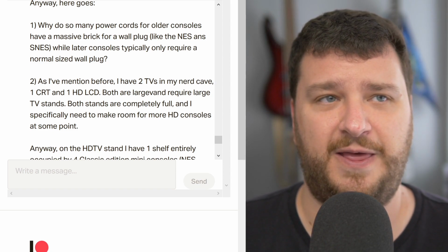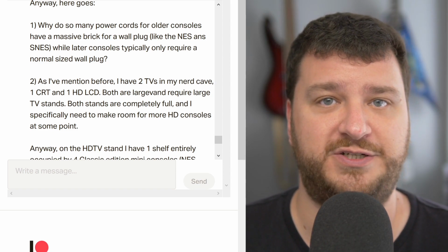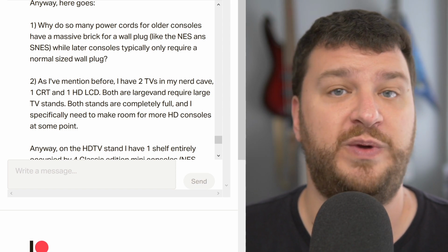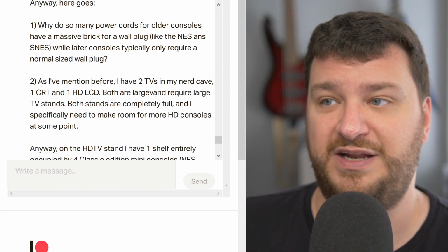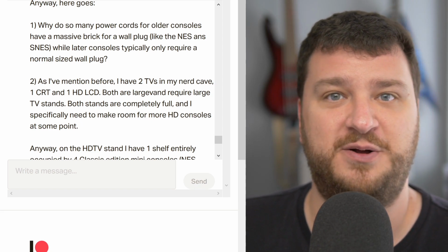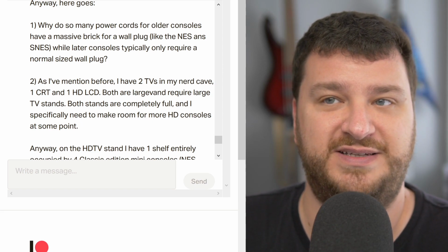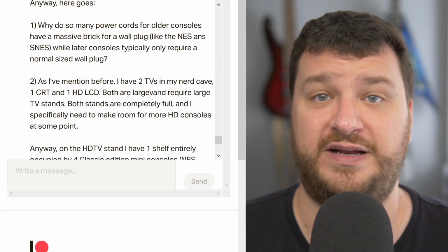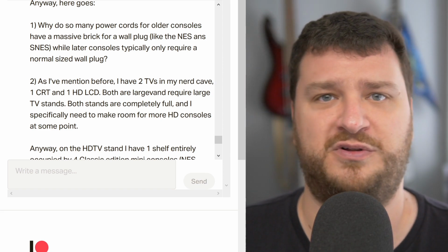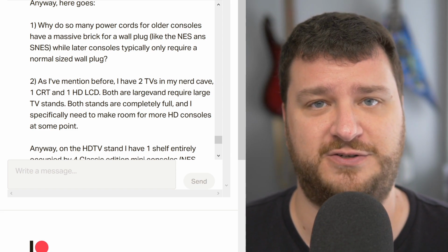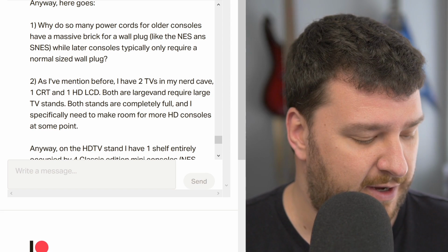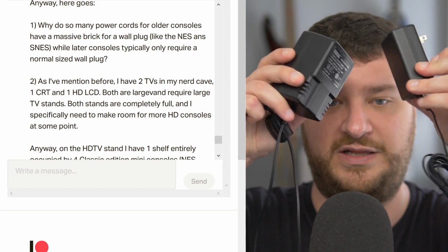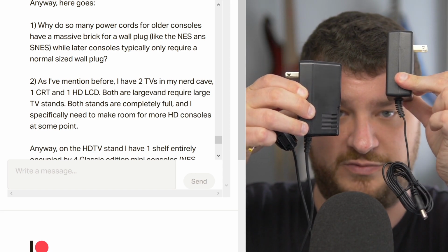But I think it's good practice, especially for small hobby projects, to have it externally. And in my experience with the computer design stuff, we made medical grade computers, and having an external brick meant that we just contacted a company that made external medical grade power supplies, and that was it. Whereas on the models where we had to integrate the internal power supply, that got super complicated, still complying with all of these certifications. So I'm a big fan of external for a million of those reasons. But also, the newer bricks use a more efficient technology, so they can be a lot smaller than the originals.